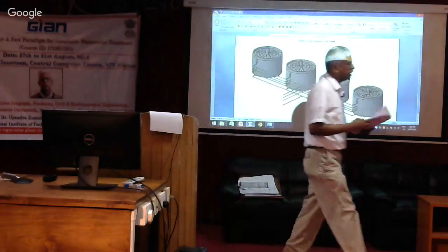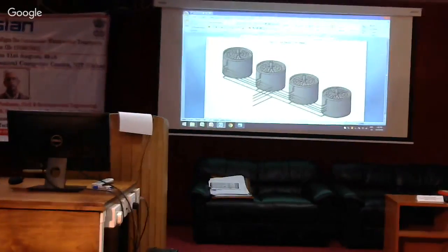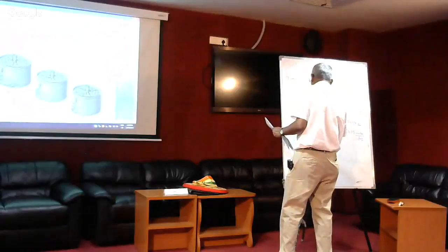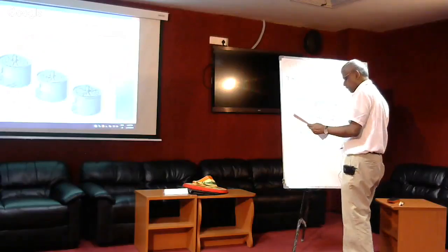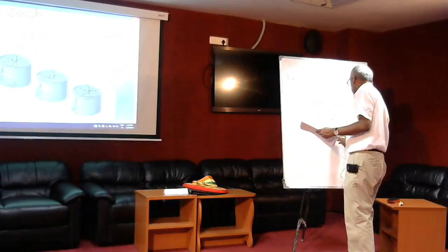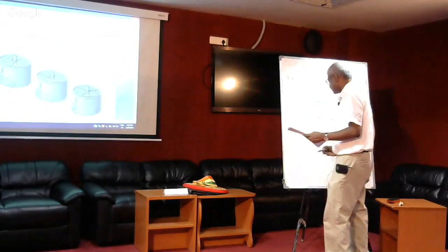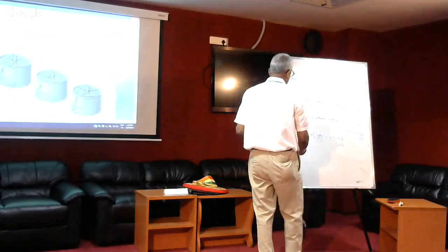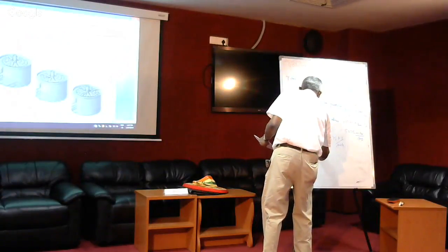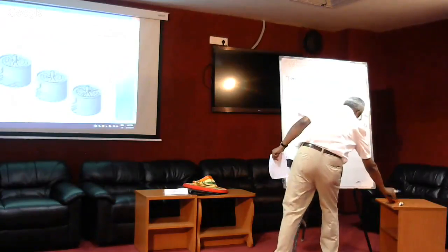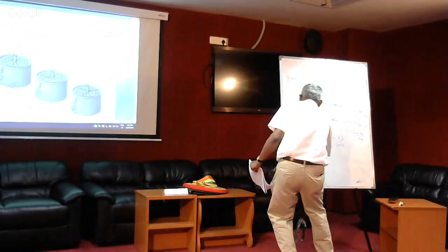Okay, so now we need the heating value of methane. Methane is the fuel. So we go to the Handbook of Chemistry and Physics and we get that the low heating value of methane is 875 kilojoules per mole. And we are producing so many moles per day. I shouldn't say heating value, I should say energy, because it's not just heat, this is more energy content.